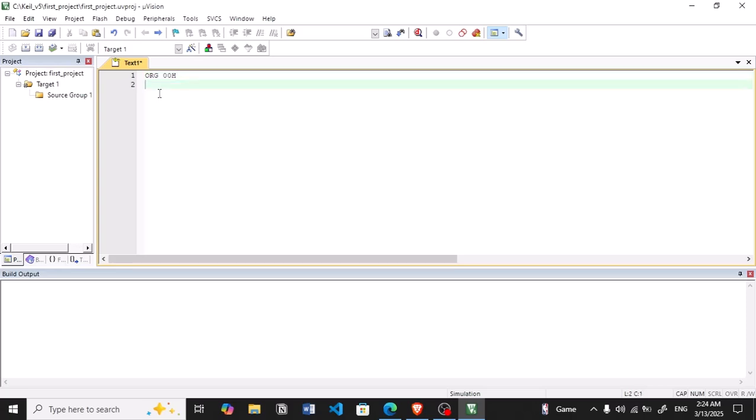After it, you have to write MOV A, and let me move some immediate value, let me call it 01. Similarly, I have to ADD with A, which is the value already available in it, another value, let me say 02, and with it you have to add this hash as well.